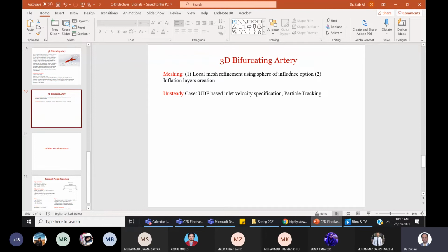If you remember last time in the 3D wing unstructured meshes, we created a body of influence. A body of influence can be any shape. In that we created a 3D box. And here we can also create another body of influence for local control of mesh sizing, which we call sphere of influence. So it will be a more spherical body.